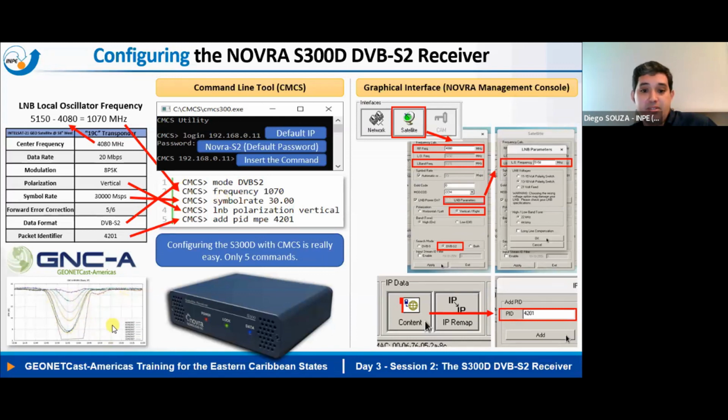during the next day. Okay, so one of the advantages of using the command line tool option is that you can automate monitoring of the reception parameters and create alerts, for example. If the signal decreases too much, you may create an email alert for your technical staff and write, hey, please check. So that's one of the advantages, right?